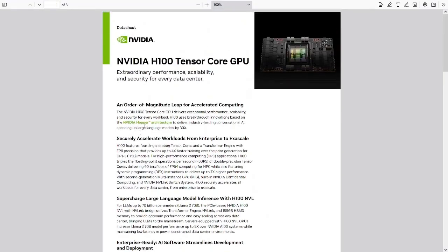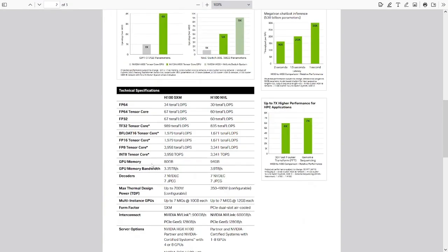And this is the data sheet for the H100 GPU. Here, we need the peak throughput and the bandwidth. The bandwidth number is clearly given, 3.35 terabytes per second. For the throughput, the picture is a bit more complex. There are a lot of numbers given, and